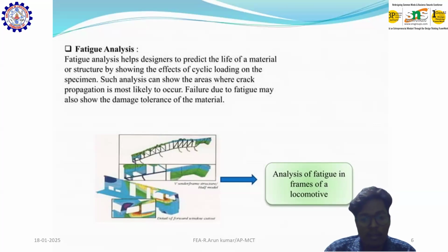For example, if I take 1 hour, I have to apply a repeated load on the object and see how the material behaves. So the engineer can predict the material life and quality of the particular material, and also find out the properties of the materials. Okay.